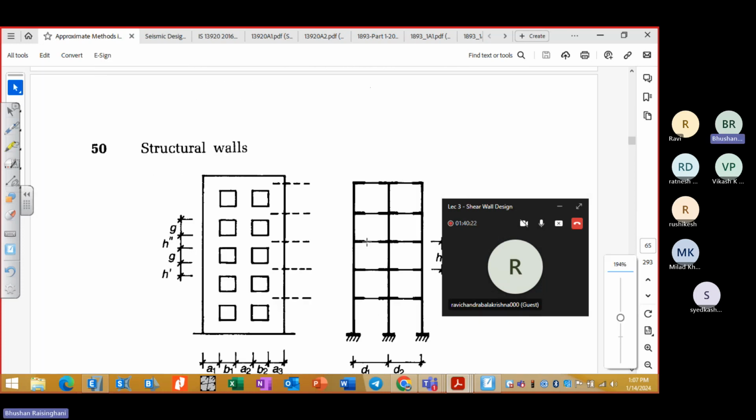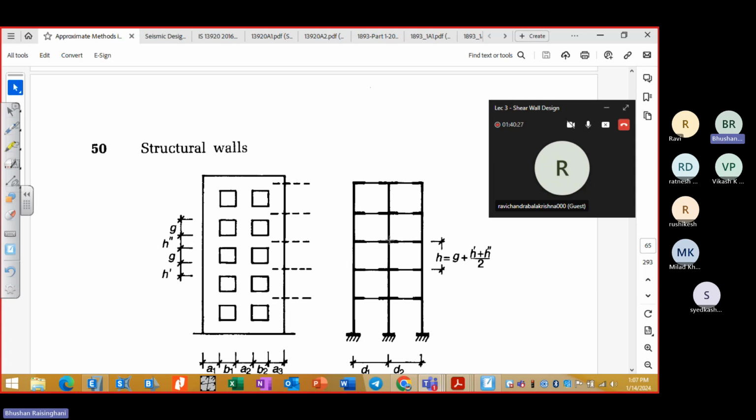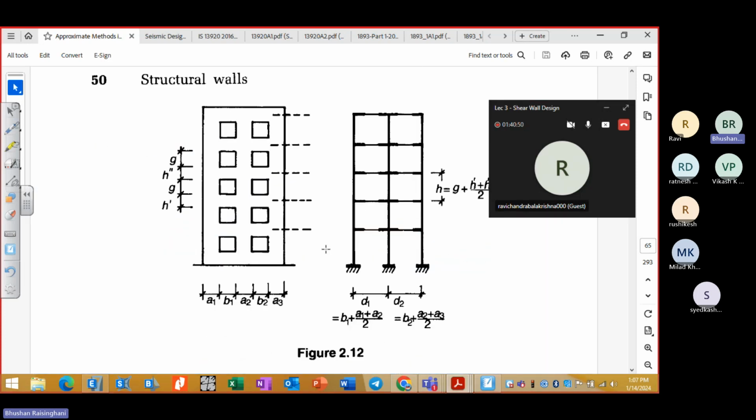These are the rigid beams we are putting at the two ends, so that they act as a coupling beam. Here you can see three columns: column 1, column 2, column 3, and in between them the rigid beams, and between these rigid beams the normal beam as well. So your coupling beam was analyzed like this for simpler analysis rather than FEM software. If you use FEM software, it can find the forces as we divide the elements, versus your simplified analysis model.